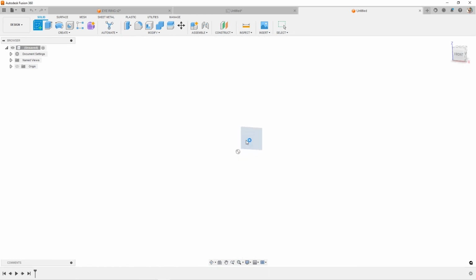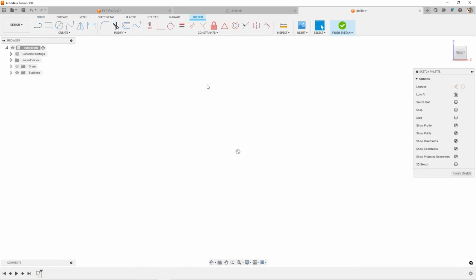Okay, new part. I'm starting a new sketch, and I'm going to do this all under one main component since I won't be adding in additional parts or anything. The first thing I want to do is sketch a center line, and that can be my construction line that I'm going to work with. Then I could work from the origin. So I'll come out. All right, so I've got my construction line. I'll start at the origin down below. I'm going to sketch a line going up.